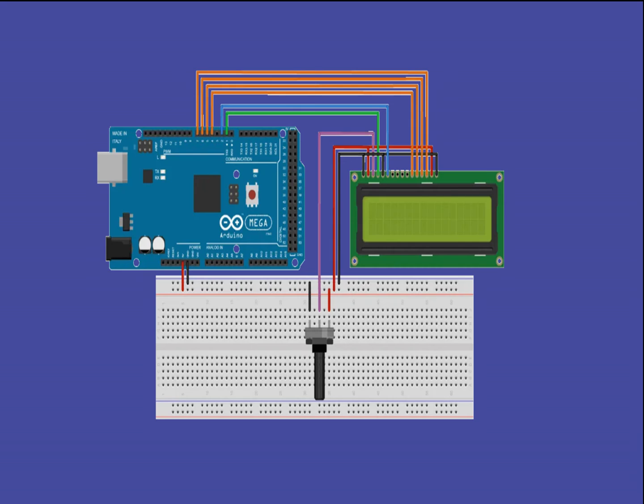One other important thing to know is how to adjust the contrast and brightness of your LCD. You will need to do this using the previously mentioned potentiometer. We can adjust the contrast of the LCD by adjusting the voltage input at the V0 pin.